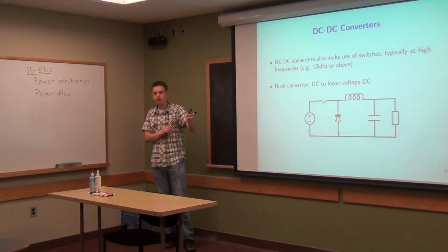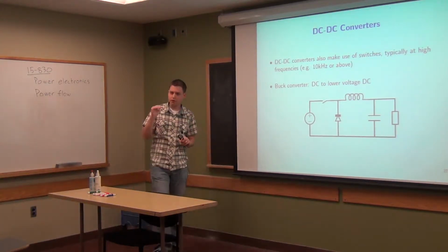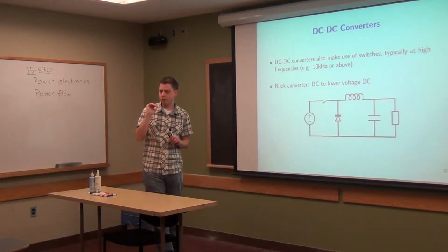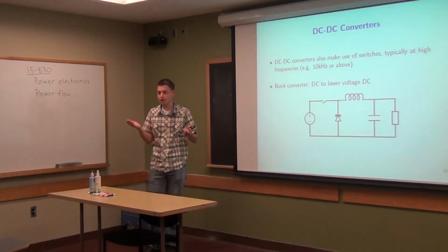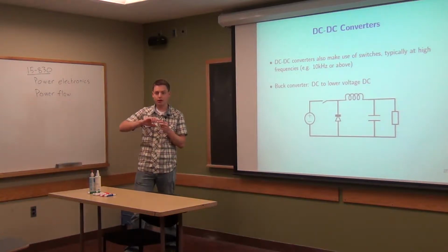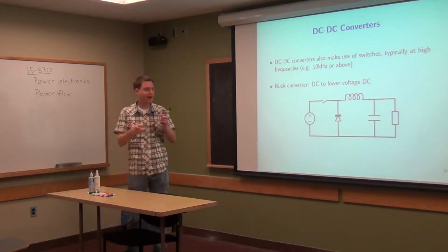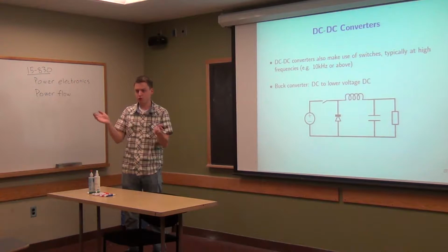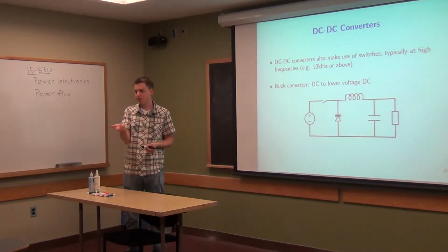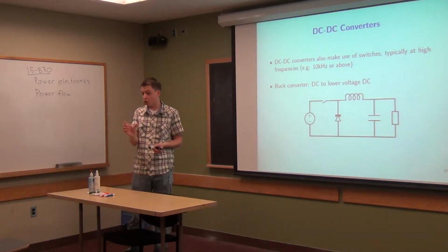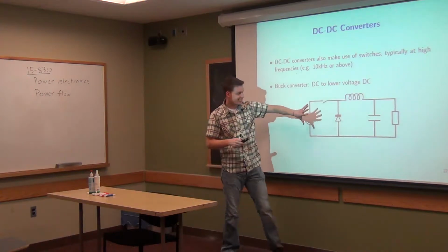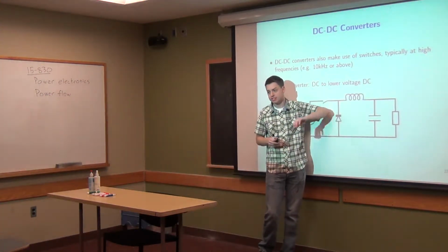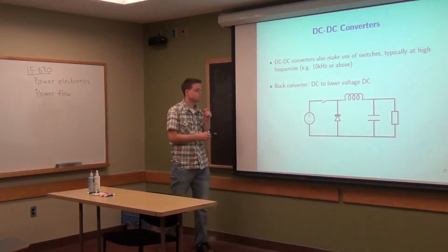And electronics really do want a very constant amount of voltage supplied to them. They use voltage for logic, so they're actually using this voltage to switch on and off very frequently to control logic. If you look at the specs for most electronics, they need a very specific voltage input. So almost all the devices you'll see have, in addition to a rectifier, a DC-DC converter in them.